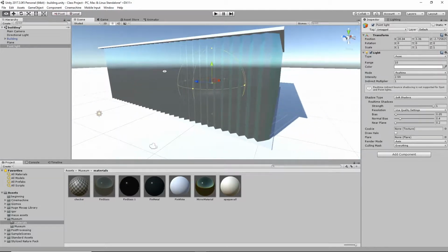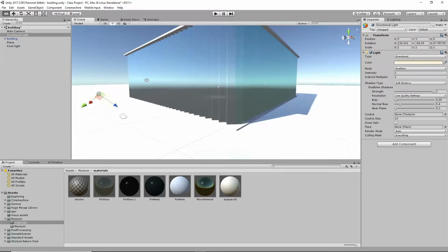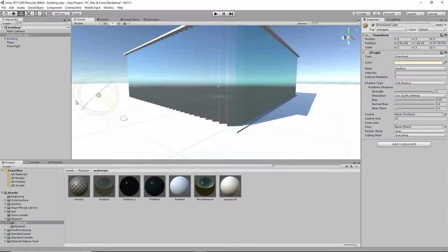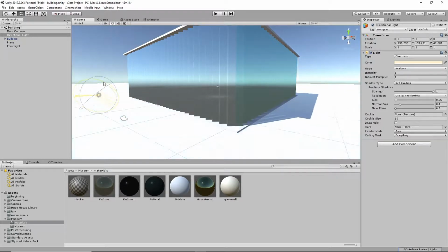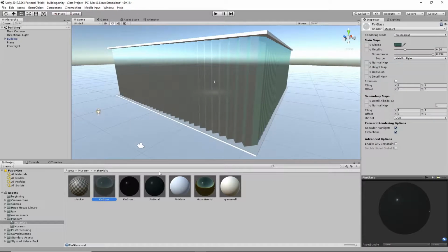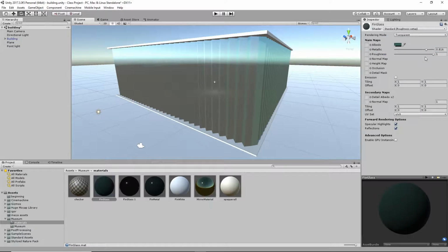You can kind of see in. It's hard to tell. Let's go. This is where you have to start playing around to try to simulate whatever your lighting setup needs to be. There's just too much reflection, I think, on that glass. So if we do, we want to crank up the metal, and maybe, nope, the smoothness doesn't affect it. So this standard roughness, maybe.